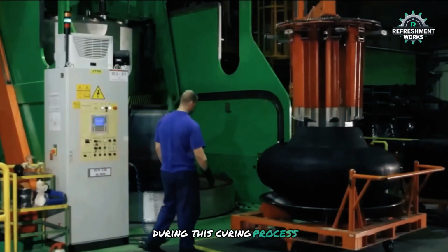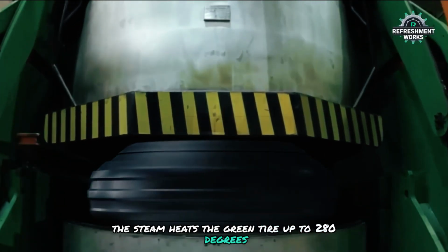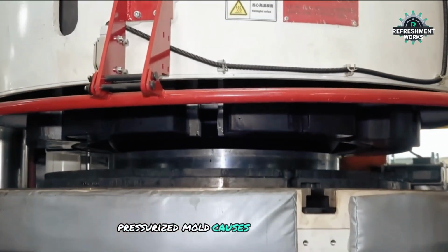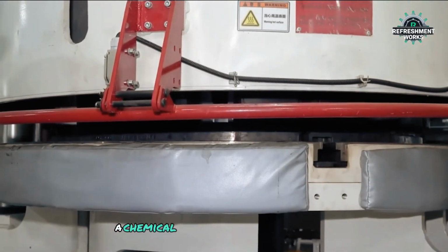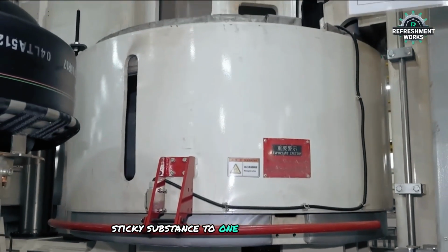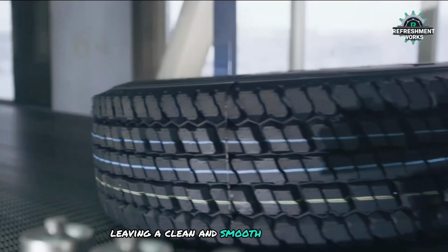During this curing process, the steam heats the green tire up to 280 degrees. Aside from the molding, the time in the hot, pressurized mold causes the rubber to vulcanize, a chemical reaction that transforms it from a weak, sticky substance to one that's strong and elastic. After curing, excess rubber is trimmed away, leaving a clean and smooth tread surface.